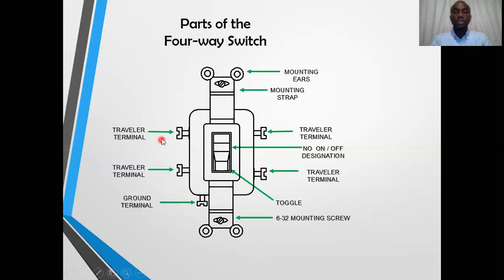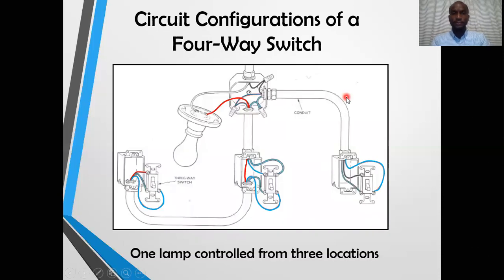Then you must use these remaining two terminals to connect to the opposing three-way switch. You will see as we look at the wiring diagram.